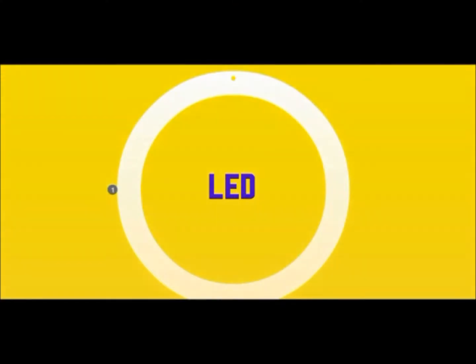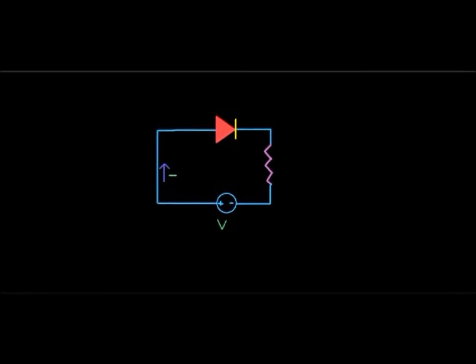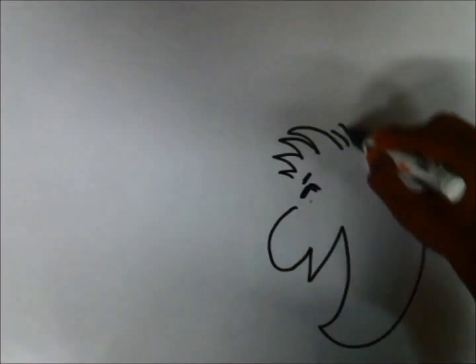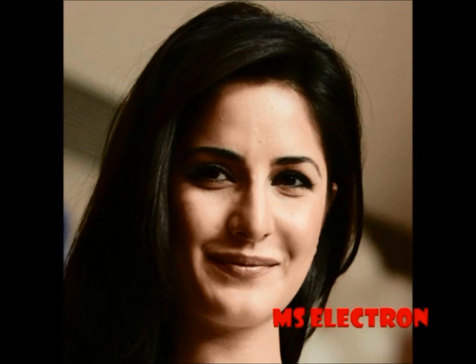Next, we talk about LED. A light-emitting diode is a semiconductor light source. LEDs are used as indicator lamps in many devices and are increasingly used for other lighting. When a light-emitting diode is forward biased, electrons are able to recombine with electron holes within the device, releasing energy in the form of photons. An array of white LEDs are used to replace the wire-bound bulbs in flashlights. Less heat is produced, brighter light is obtained, longer battery life. That's good news for the ecologists.